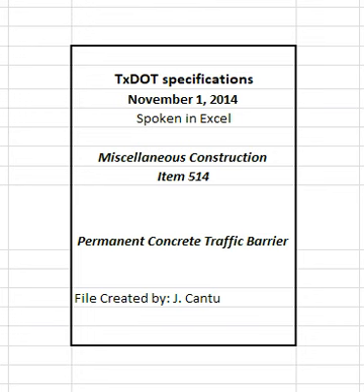Form cure or water cure concrete, except for precast sections, for at least 4 days, or cure with Type 1D or Type 2 membrane curing compound. Cure precast sections in accordance with Item 424, precast concrete structural members, fabrication, TxDOT. Remove concrete, mortar, oil, and other substances leaked onto the roadway. 3.2 Cast in place barrier.